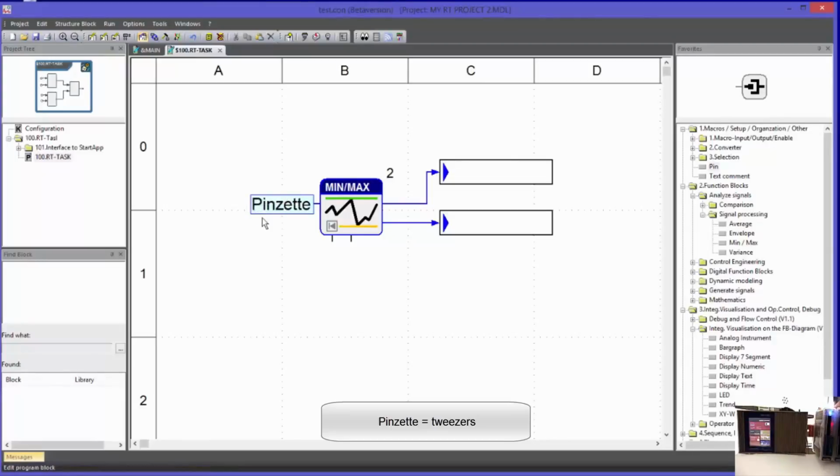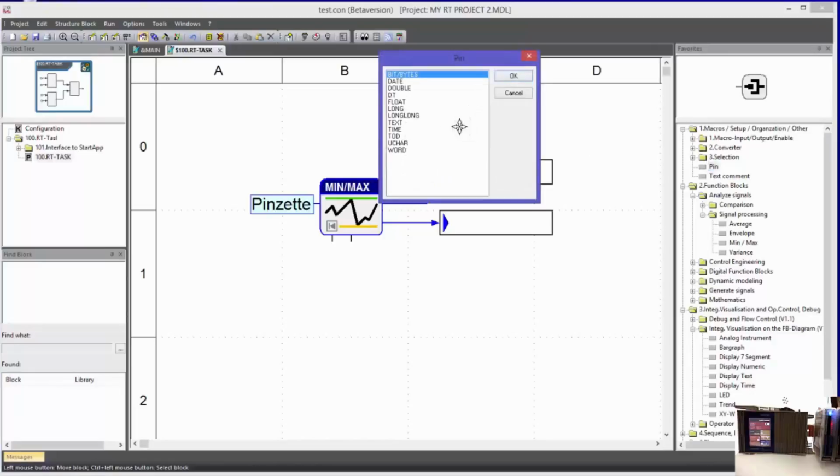In part 1 we have already connected the I/O variables to this min-max block over the block attribute. I could now connect the application connectors to this output of the min-max block. As you can see, a block has already been assigned here. That is why I will use a special block, an auxiliary block of the type pin. This pin block is used to create a breakpoint to block attributes.